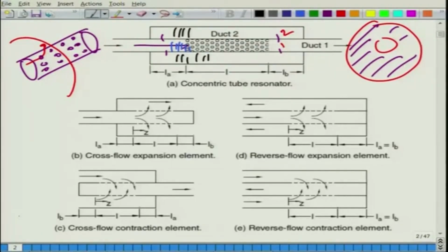So, one thing that I mentioned at the very outset, at the very beginning, is that coupling between the planar wave propagation here in the duct 1 and the annular cavity duct 2 really happens through the mass exchange, that is basically from the continuity equations in each of the ducts. Because of the annular cavity, some part of the fluid is going inside the control volume here, we will do a thorough analysis, and some part can also come inside. So, it is like the exchange between the acoustic masses, exchange between the ducts 1 and 2 of the acoustic masses leads to an additional term in the continuity equations in each duct, duct 1 and duct 2, and we will see how this kind of affects the development of equation.